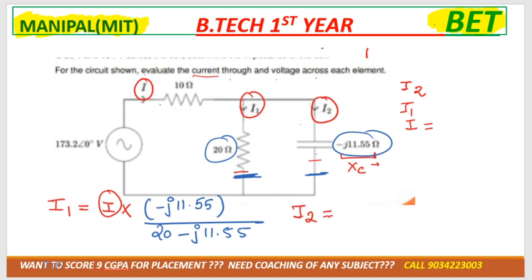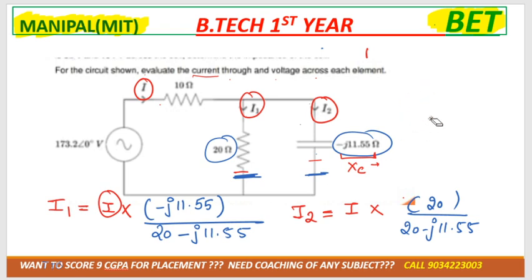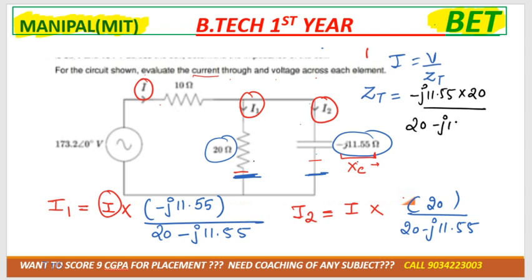Similarly, now you tell me what would be the value for I. So how can we get I over there? I is total voltage divided by the total impedance. So for that we need to calculate the total impedance. Total impedance is how much? These two are in parallel. So suppose this is XC, that means minus j 11.55 multiplied by 20, divided by 20 minus j 11.55, right?